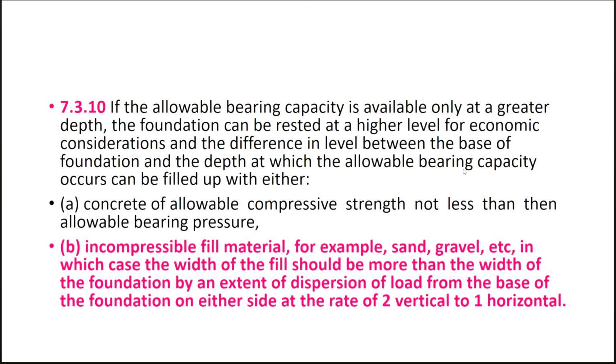Now, we were talking about if the allowable bearing capacity is available only at a very, very great depth, then how do I rest the foundation? And that too at a higher elevation. So what they say is that I can go for an incompressible fill material, for example, a sand or a gravel, in which case the width of the fill should be more than the width of the foundation by an extent of dispersion of the load from the base of the foundation on either side at the rate of 2 vertical to 1 horizontal.